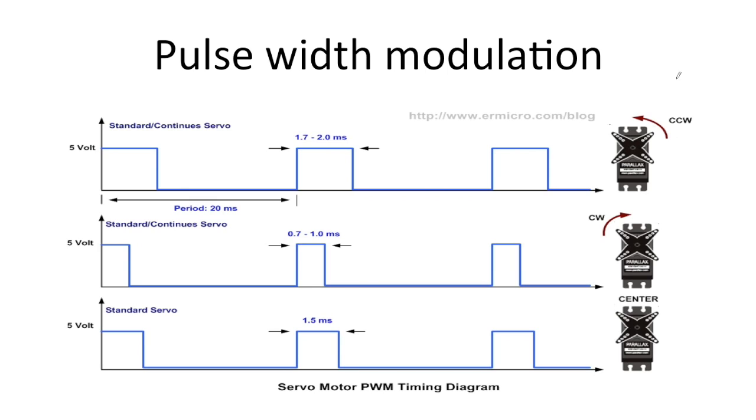Let's take a look at an example of an application of pulse width modulation. So here is our microcontroller, and we can connect one of the output pins to the servo motor. You cannot drive a servo motor with just a simple 1 or 0. You need to supply it with a constant pulse of square waves. By varying the duty cycle, that is the amount of time the pulse is on with respect to the rest of the waveform, we can control its direction of motion.